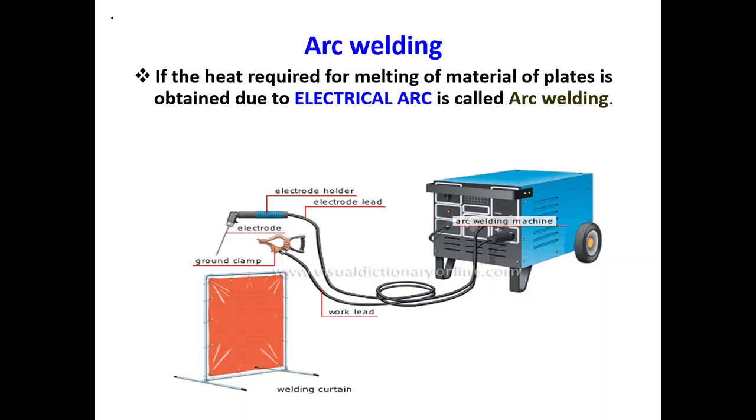Now next, the arc. The temperature after the arc is formed is high. The metal at this temperature becomes reactive to oxygen, nitrogen, and hydrogen in the air. The mechanical properties are seriously affected by this reaction. To protect the weld from this, shielding around the arc is required. This is accomplished by covering the electrode tip, arc, and molten weld pool with an envelope of gas or flux or both, which prevents exposure of the weld metal to air.